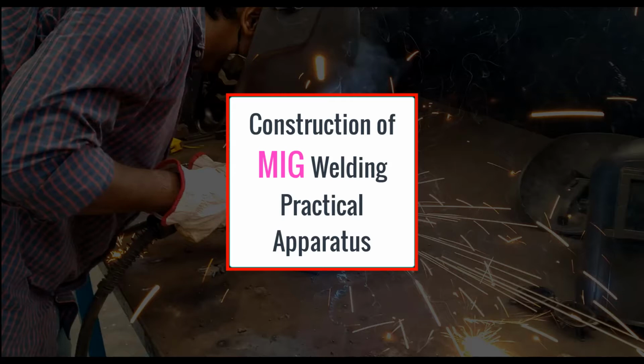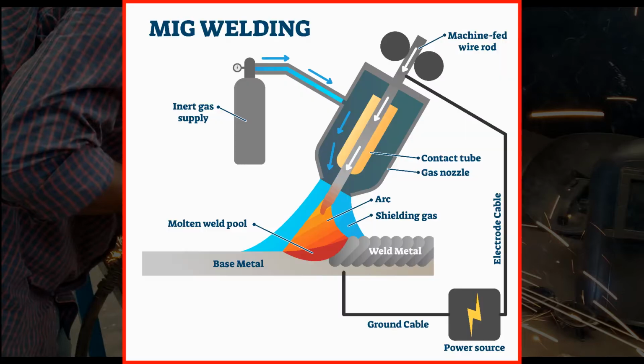We use the inert gas to save our work material from oxidation. We have to avoid contact of our weld pool, or weld zone, with the atmosphere, so we use the inert gas.